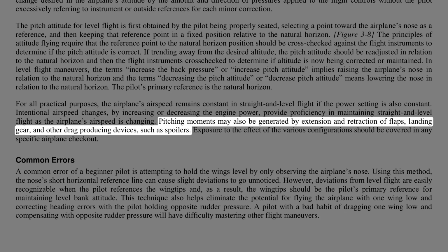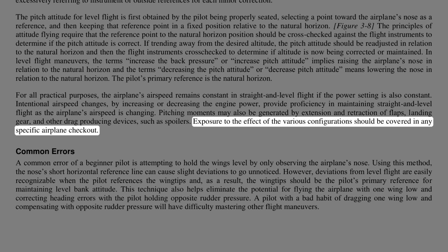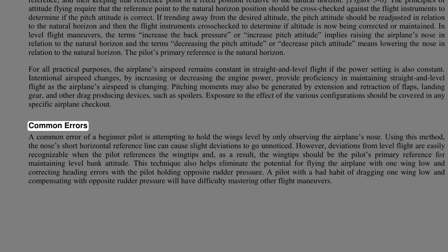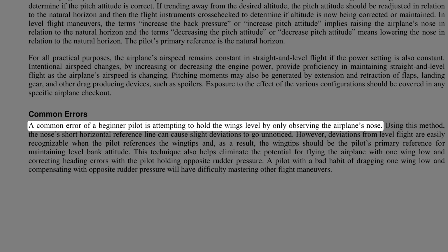Pitching moments may also be generated by extension and retraction of flaps, landing gear, and other drag-producing devices, such as spoilers. Exposure to the effect of the various configurations should be covered in any specific airplane checkout. Common errors. A common error of a beginner pilot is attempting to hold the wings level by only observing the airplane's nose.